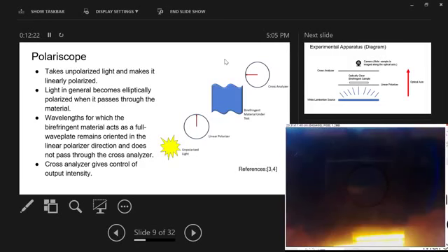And then finally, we can look at the output, those birefringent patterns that I was showing you earlier, by the cross-analyzer, which actually ends up controlling the intensity of the output. So the isochromats can be seen at any angle because, in general, the light that's emitted from the isochromats is elliptically polarized. So, a component of that will pass. But that from the isoclinic, since it has 0 phase retardation, will remain linearly polarized after it passes through that.